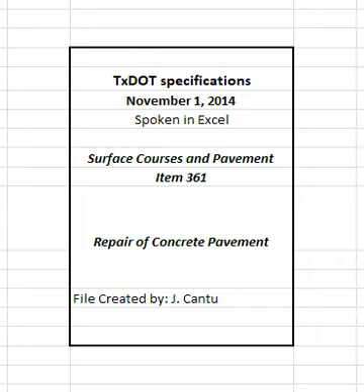Drill. Use a maximum 40 pounds drill with tungsten carbide bits. Air compressor. Provide compressor equipped with filters designed to remove oil from the air and capable of delivering air to remove dust and debris. 4. Construction. Submit for approval all materials and methods of application at least 2 weeks before beginning any repair work. Repair locations will be as indicated on the plans or as directed.